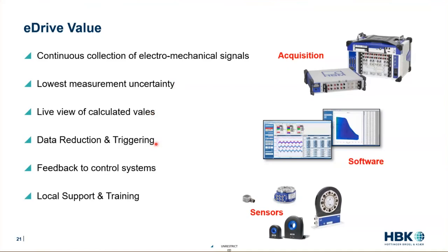If you're running a test for 80 days and you're measuring a 10 kilohertz inverter, that's a lot of data. We have some really cool data reduction techniques and triggering techniques so that you can do these long-term tests and still catch those really short events. So you can have your really long data stream trigger, have high frequency events, and really see how that inverter is functioning during some of these faults.